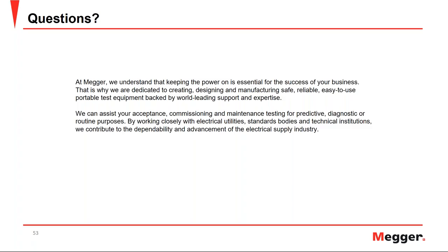If your losses are increasing at lower frequency, it's an early indication that your power factor values at 60 hertz are going to increase in the future. The whole idea of preventive maintenance is to pick up problems at an early stage and prevent failures, and that's what narrowband DFR does for field engineers. It gives an early warning about what is about to show up in 60 hertz testing.